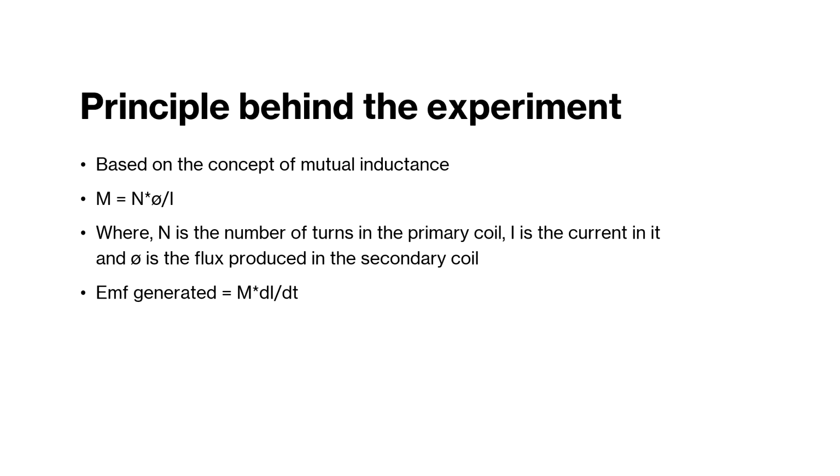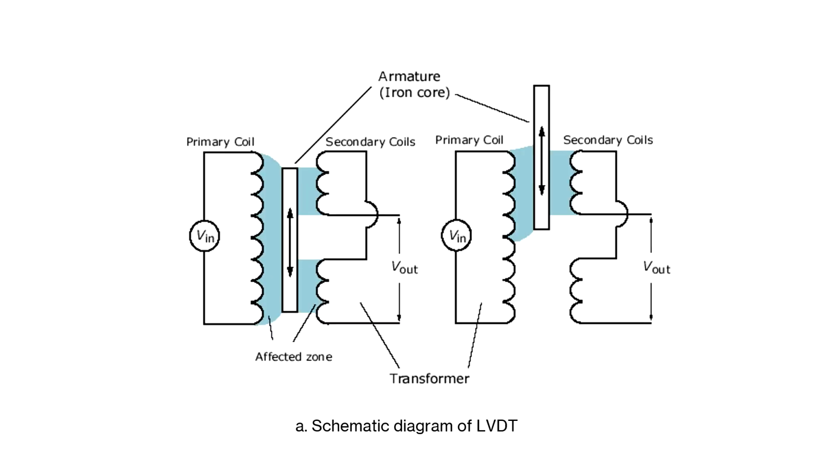Now, this whole experiment and concept will help us to measure the displacement of any core or any sample in this setup. This is a schematic diagram of LVDT. On the left is a core at the null position, and on the right, we can see a displaced core.